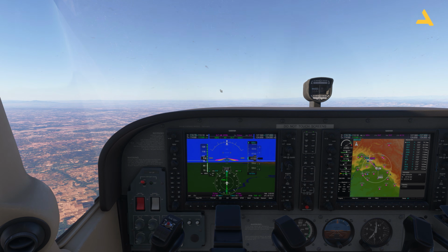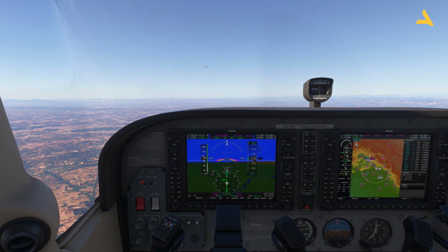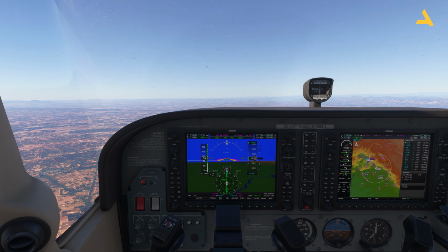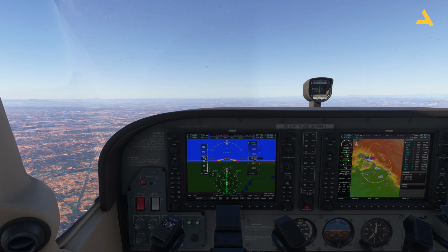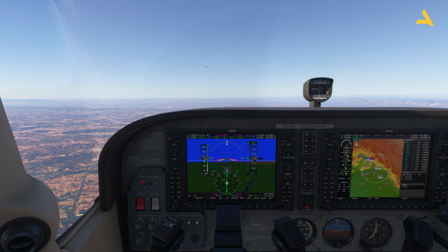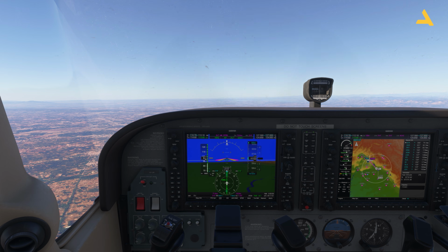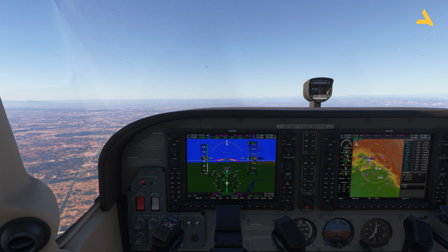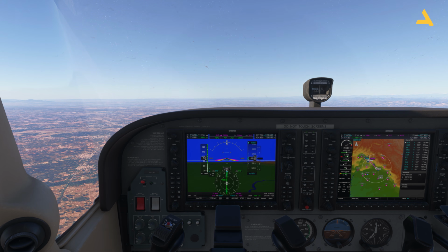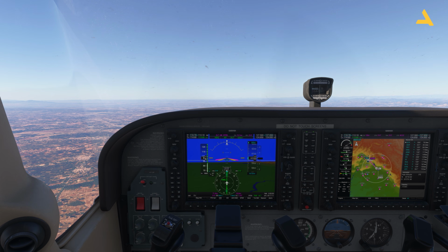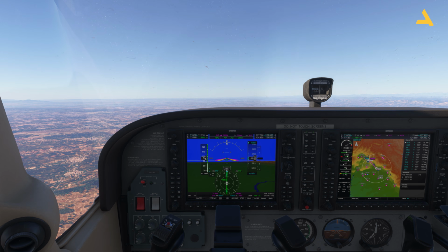That's why I call G1000 one of the most powerful navigation devices in Microsoft Flight Simulator 2024. If you are comfortable with this device and you know how to make your flight plan and do VOR navigations and your GPS flight plans, plus NDB navigation, I will also tell you how to follow the NDBs. But that will be a separate video because it is just like the VOR. The procedure is slightly different for its frequency, but you can also track the NDBs, which are non-directional beacons. Even they are older than the VOR.